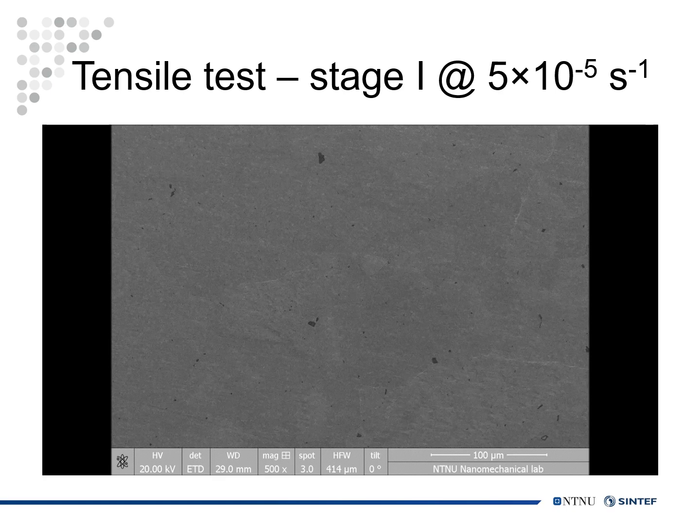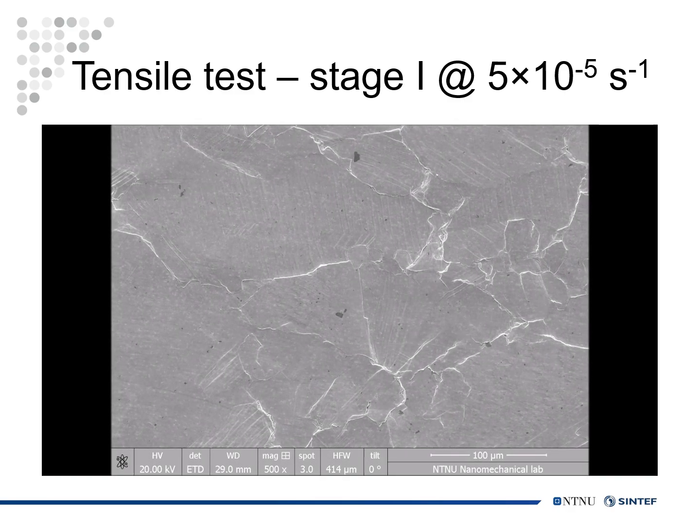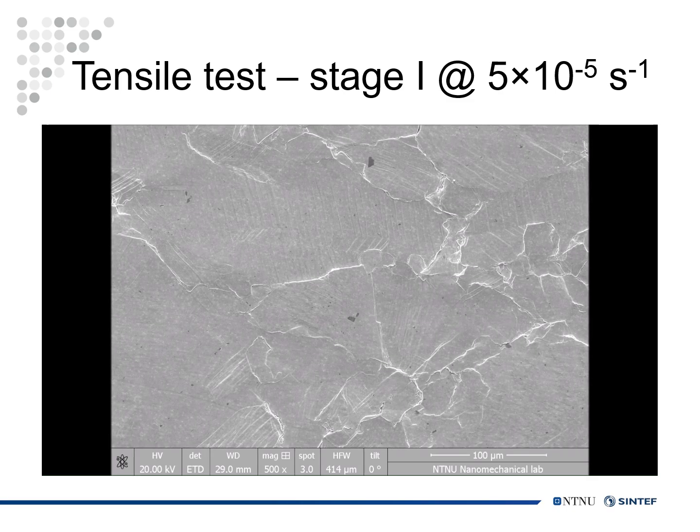Based on the microstructure evolution, we have divided the tensile deformation into 3 stages. In the first stage, we see deformation accumulation along the grain boundaries, such as here, here, and here. The slip lines occur inside the grains with a single direction, such as this one, this one, this one, and this one. Some damage can occur at grain boundaries, such as this one, but no significant change close to the precipitate faces, like this.